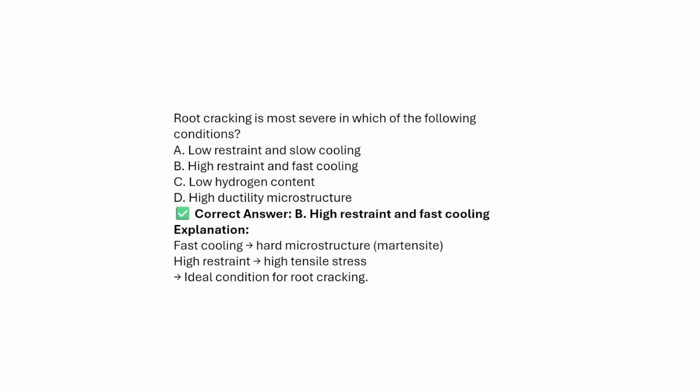Next, root cracking is more severe in which of the following conditions? A, low restraint and slower cooling. B, high restraint and faster cooling. C, low hydrogen content. D, high ductility microstructure.